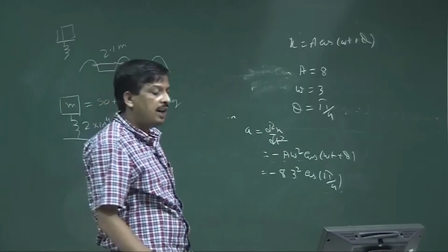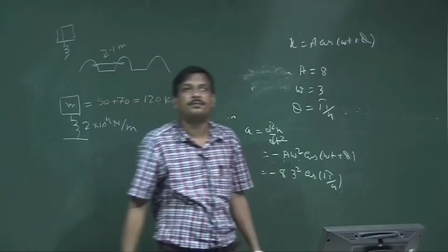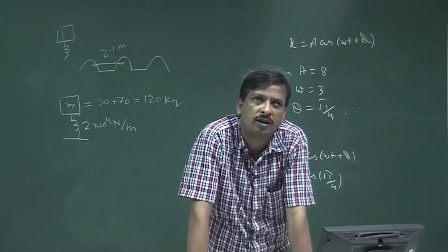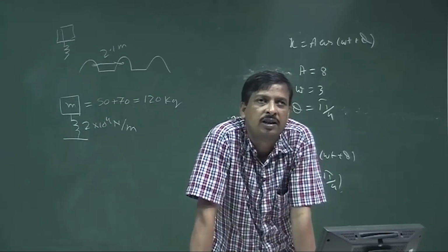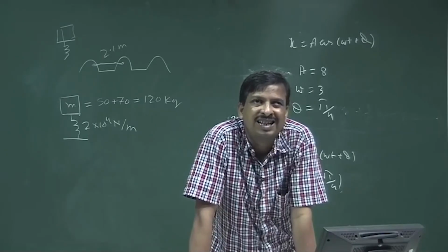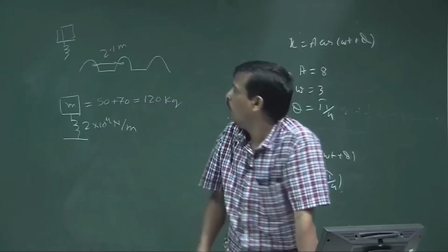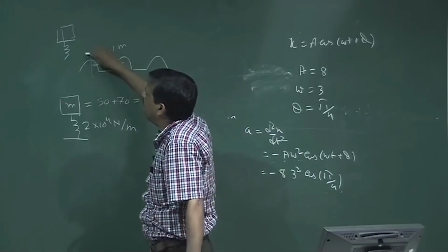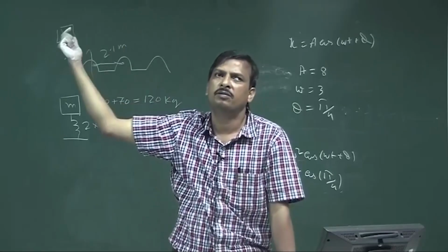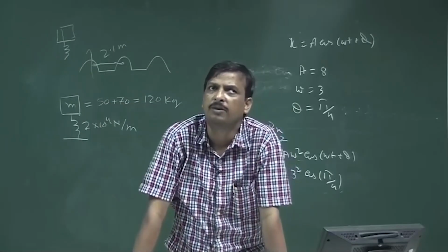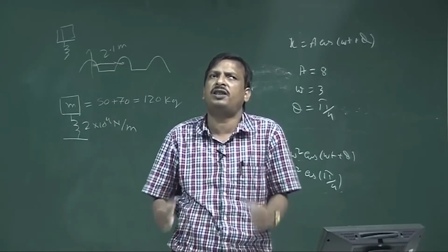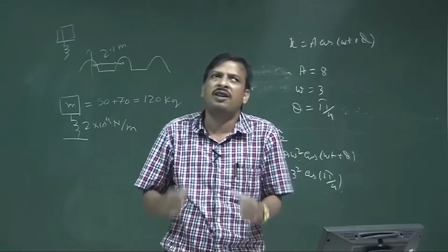Okay. Now, I said, will an accident occur? So, after you know the mechanical oscillation, what will you say? That if the tractor seat resonates with the force received from that bump, then the driver will be uprooted from the seat, because if the system resonates, maximum power transfer will happen. So, the driver cannot hold the seat. Okay. So, an accident will occur.